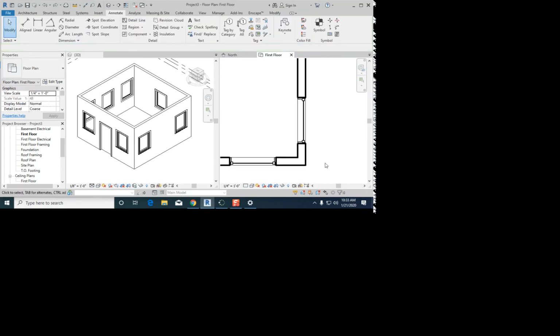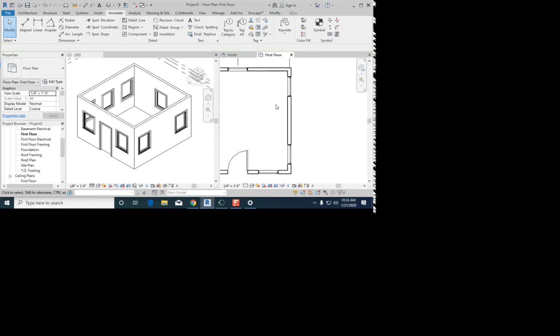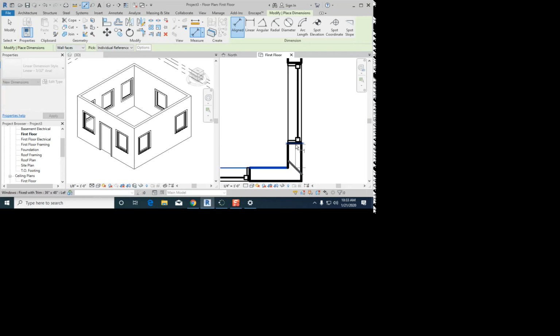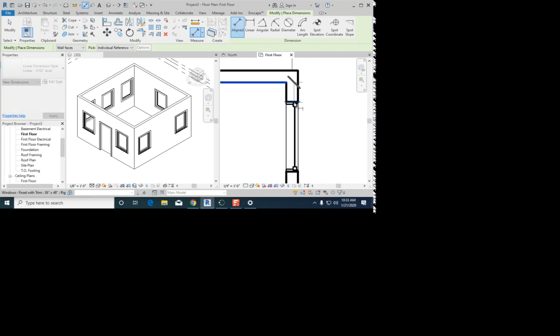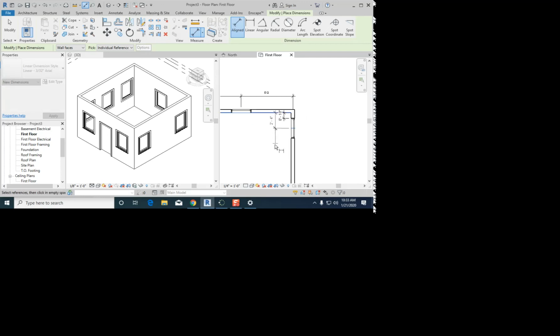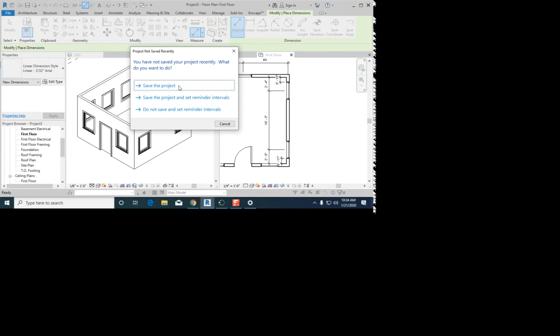I'm going to do that one more time in case I lost you somewhere. I'm not going to do the call out like, does anybody need me to do it one more time? I'm just going to do it. DI. So check wall faces. This time I'm going to start from the bottom, come up to this edge, place it. This time this face, this edge. One more click in the middle of nowhere. And then since I'm still dimensioning, I still don't need to hit escape. Here. Okay, and now that I'm done, I'm going to hit escape twice.